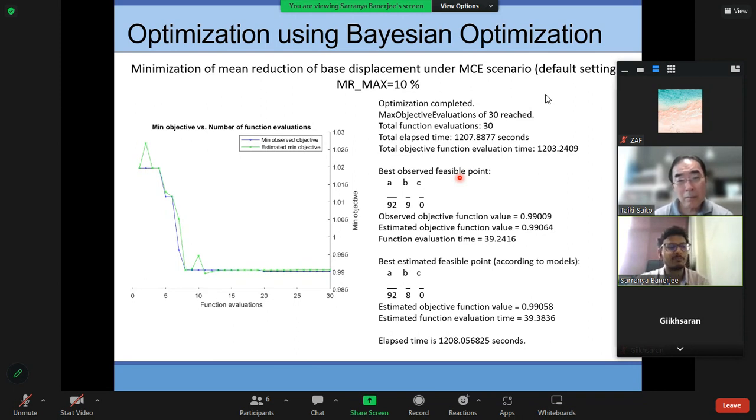If we have the unbonded isolator with a base displacement of 820 millimeter, we would like that to reduce to 770 or say 600 millimeter. And if with the isolator the base displacement is say 450 millimeter and it gets reduced to 400 millimeter, that also has some importance. But in the overall scenario, we want the maximum to reduce, right?